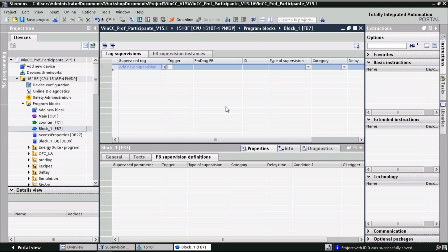By the way, I don't know if you know that, so every time I tell you something new: when you select the PLC and just press the F7 button, you can actually search for FBs, FB numbers, names, whatever.